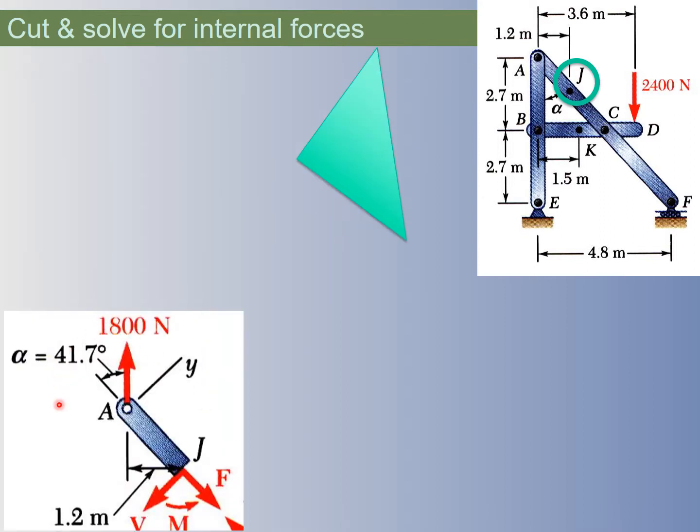So let's just look at the top piece here. Okay, here's just a close-up of the top of this beam, and we need to make sure that all of the forces in the axial direction, the normal direction, and the moment add together for this. So look at the orientation of our coordinate system. We're going to orient our Y direction with the shear force and the X direction with the axial force.